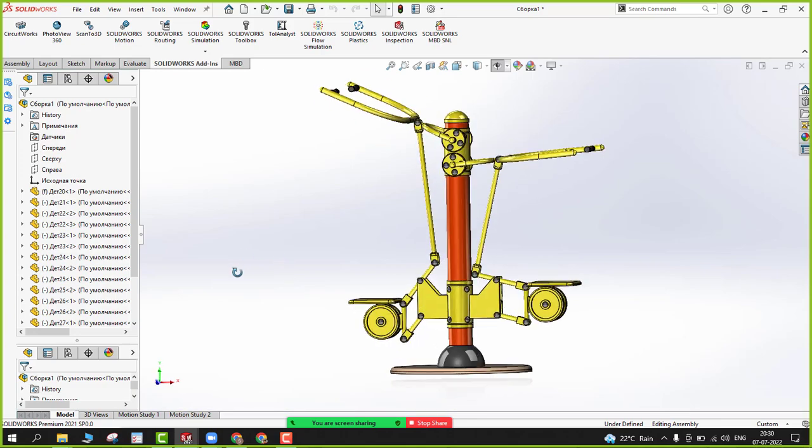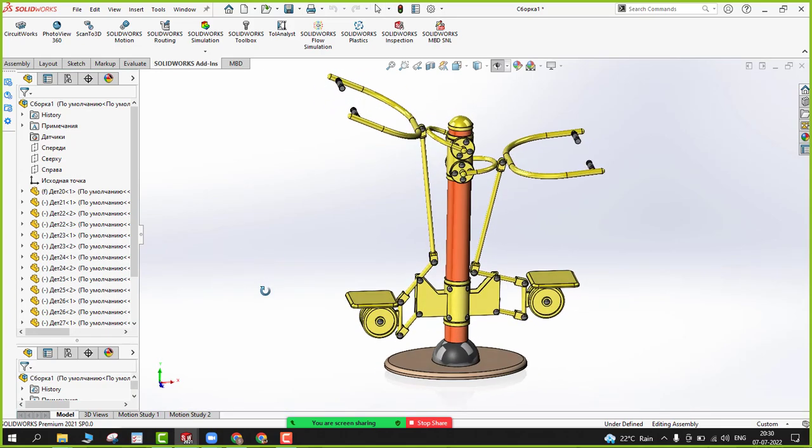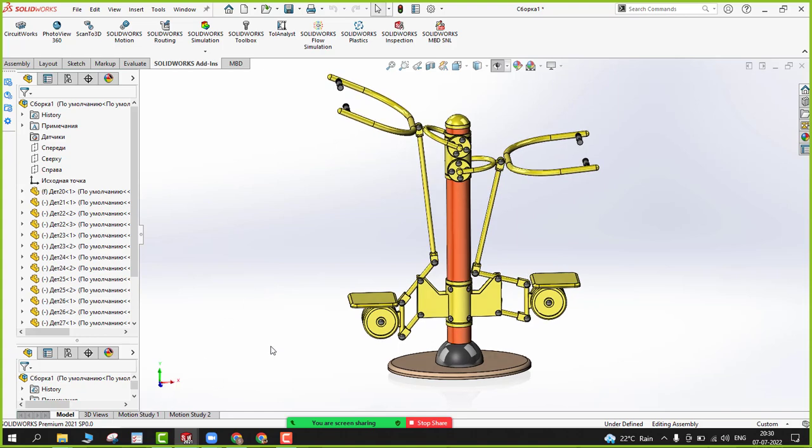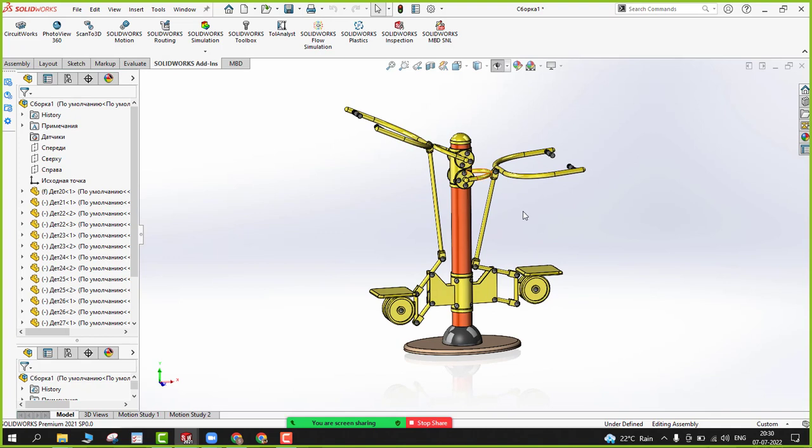So this is the model. The first thing is you need to rearrange it however you want. To create the first one, I'll make it normal to view. You need to align these two parallel to each other so that if you move this, this also should move like that. You need to define the motors for that. Now let me showcase how to create the new animations, to animate everything and to create the rotational animation as well.